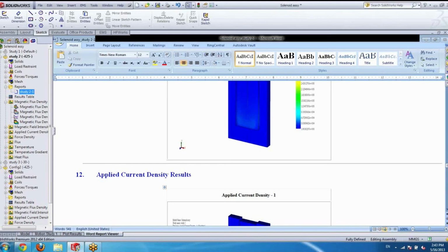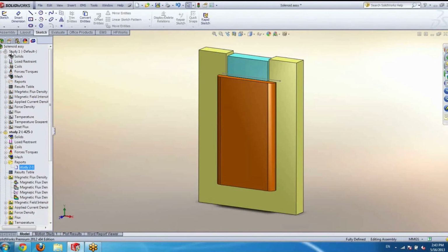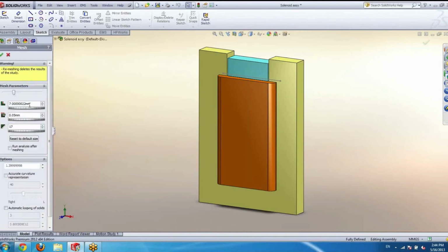And so all the other configurations, they usually tend to mesh. Now, in the event that happens, you have the option again of going into that configuration. For instance, if you can see here in my model, I have the mesh of each configuration. So what I can do is activate, let's say, this one, and I can go in here manually and tweak the parameters of this mesh to make it mesh.